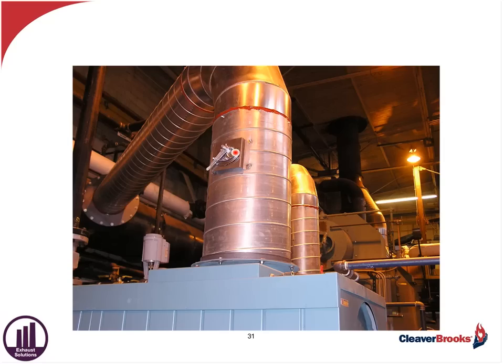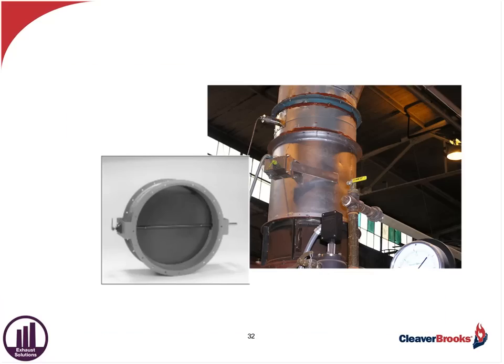I might have to adjust it in the winter, or I may have to adjust it again in the summer, but it's just a mechanical damper. So sometimes those are used. Other times the variation could be quite extreme, impacted by velocity outside, wind velocities, downdrafts, varying temperatures, barometric pressures, and so on.